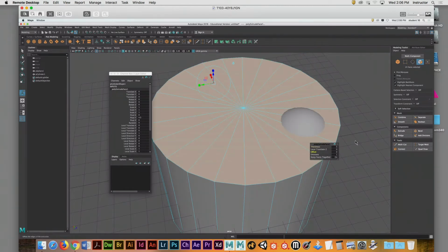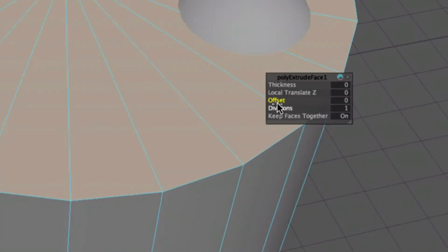Same thing goes for in here. If you select the option, just like the channel box, if you put your cursor over here and middle mouse click and drag, now it's interactive. You can also do it, this is an interactive slider. If you want finer values, hold down the Control key. Now we're going to get finer attenuation in those values.